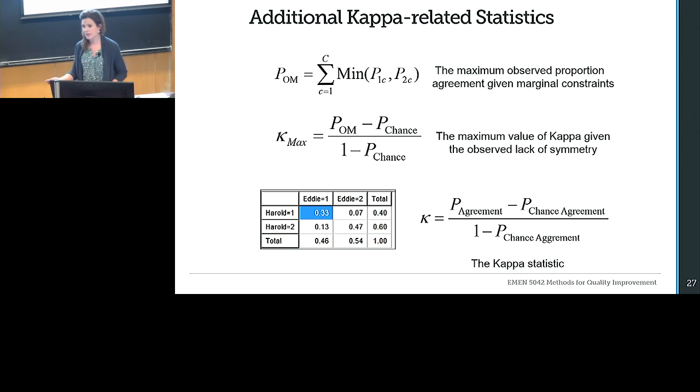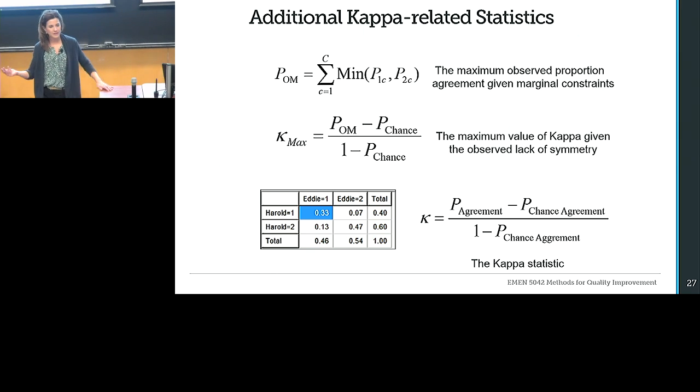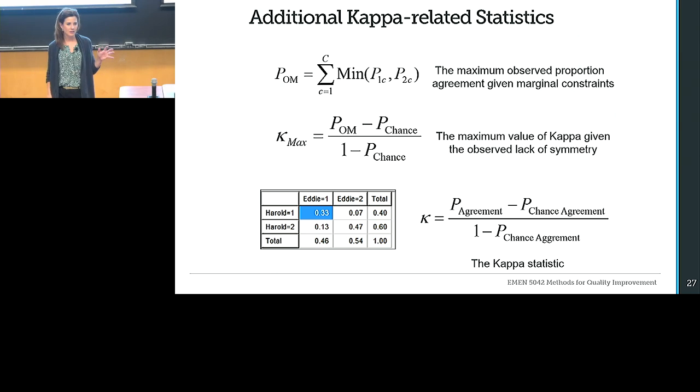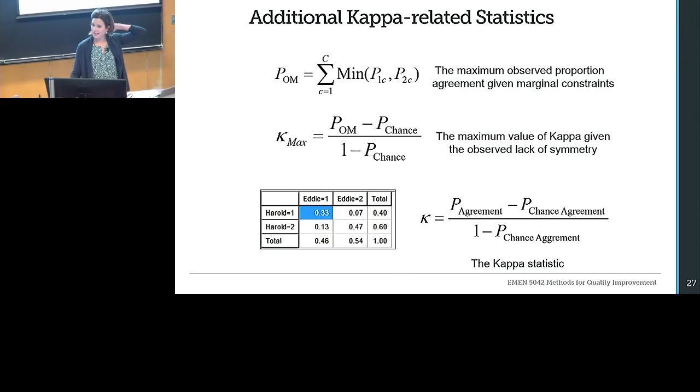Now, when we calculated our P to T ratio, we did the percent measurement error due to repeatability and reproducibility, and so we had some idea. Similar type of thing here but it really will have to do with how are we using the scale and how are we assessing items. There could be differences between that. And so we might have to make some clarifications on what the scale really means, or we might have to make some clarifications on how you assess items. It all comes back to training. Both ways comes back to training, but what area you focus in might be different.